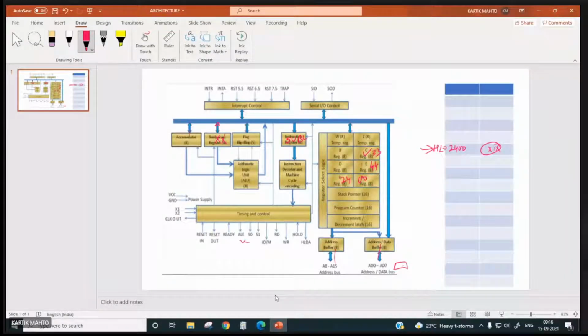So 33 will be copied over here. Now A minus 33 will be done, minus the carry flag. That's why this carry flag is here, in this direction. So the carry flag will be subtracted whenever the instruction SBB C is there. Then C will be copied over here. Now A minus C minus carry flag will be done, and the result will be stored back over here.